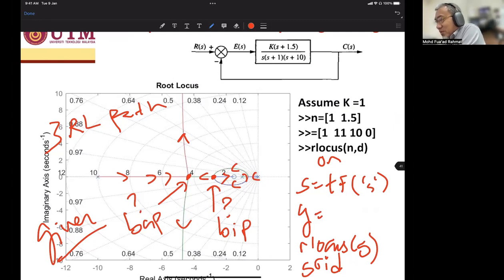Okay, so take note the break in and break away point ended at infinity. And infinity over here. So we have one break in point. We have 2 break points. The first one is break away, and the other one is break in. Okay, we have 3 root locus paths, and there is no root locus cross at the imaginary axis.